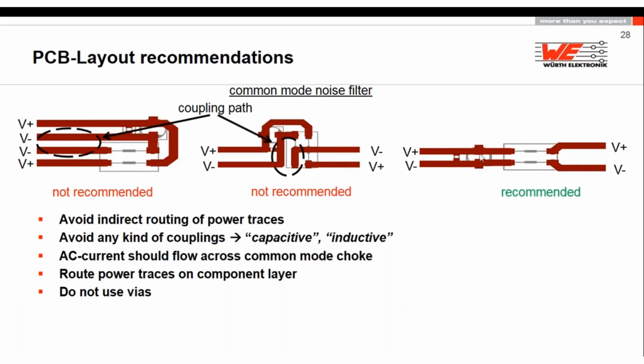With redesign number three, here you can see capacitors and the common mode choke and the exit. With this one, he passed the EMC test and he was happy. If I would not see this first design, I would not believe that such a small PCB, wrong PCB routing, could make such a crucial effect. You're not talking about 2 or 3 dB, you're talking about a 15 to 20 dB difference. So please be aware, if you filter something, to not cross or be too close to the cleaned and filtered area.